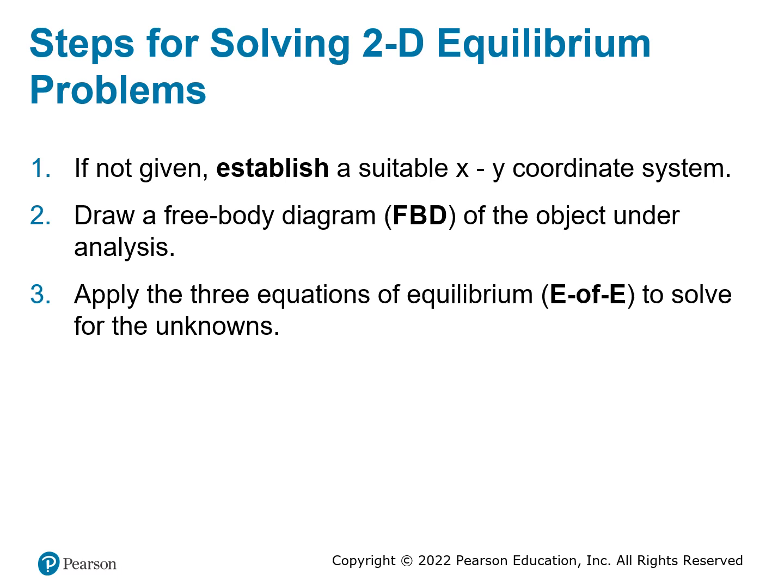Now let's look at the steps to solve a 2-dimensional equilibrium problem. The first step is to select the coordinate system, because in a real situation, it doesn't have to be horizontal and vertical. It could be an angled direction, depending on the device shape. So you want to select the proper XY direction so you can find out the angle of your vector. The second, which I think is the most important thing, is to draw a correct free body diagram.